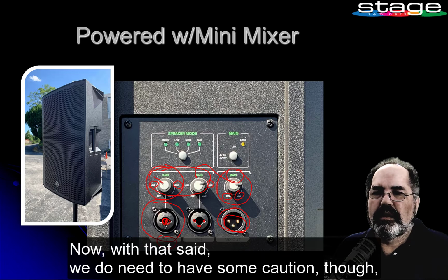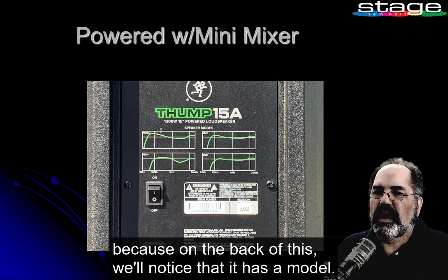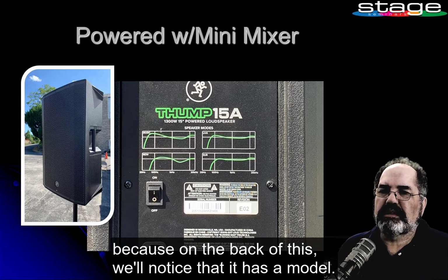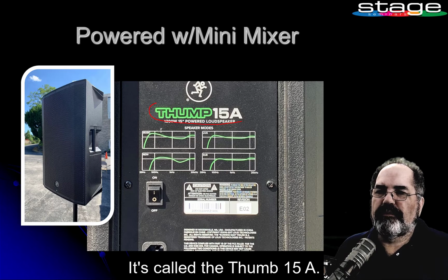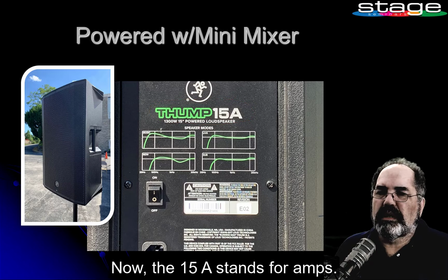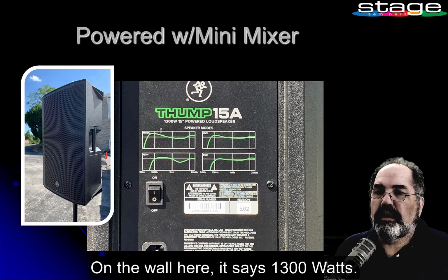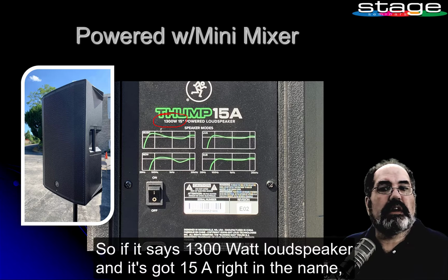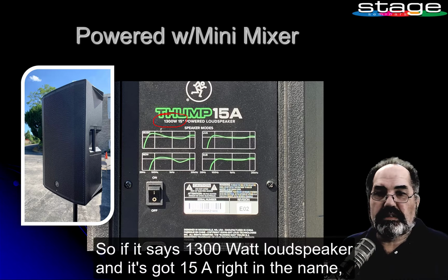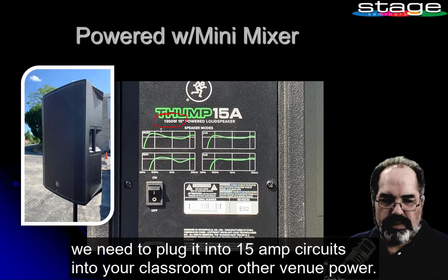Now, with that said, we do need to have some caution though, because on the back of this, we'll notice that it has a model. It's called the Thump 15A. The 15A stands for amps. It tells us what kind of circuit we can plug it into in the wall. Here it says 1300 watts. So if it says 1300 watt loudspeaker, and it's got 15A right in the name, we need to plug it into 15 amp circuits in your classroom or other venue power.